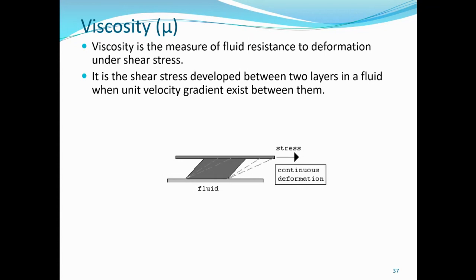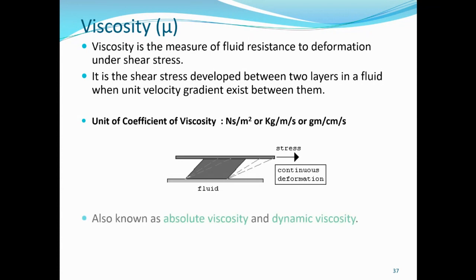The velocity of the fluid at different layers is different, and this is because of the shear stress itself, or because of the viscosity, and the no-slip condition, which retards some layers, those close to the boundary.